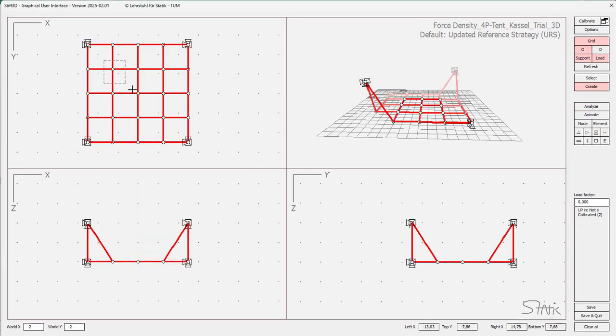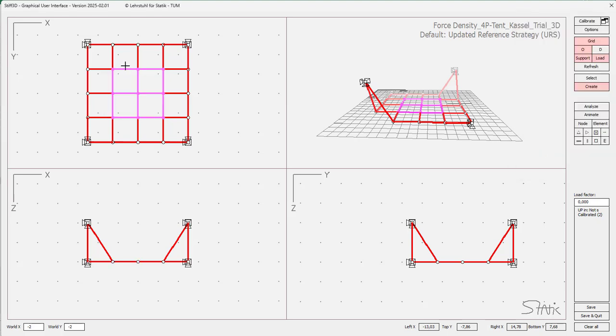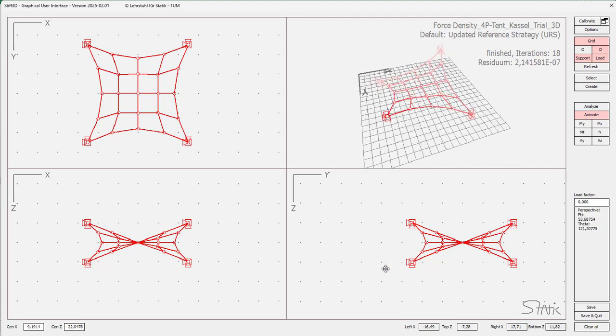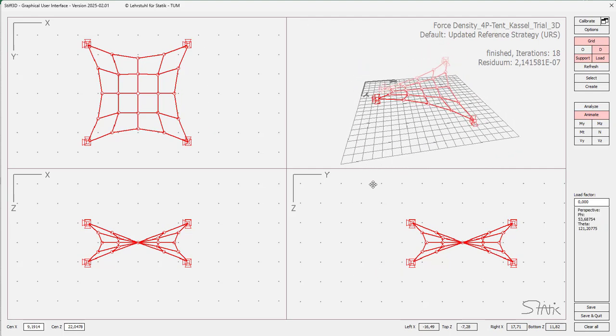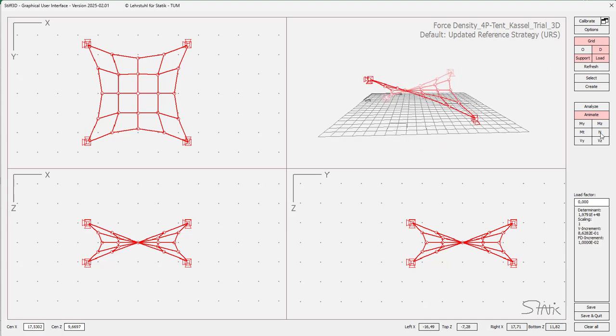And if we constrain the lengths of these inner cables, not these, additionally to the goal length of 2, deselecting, then we receive this result, which looks perhaps even more harmonic with the controlled lengths of the edge cables and this interior one. If we just look at the 3D appearance, I think we can accept it.